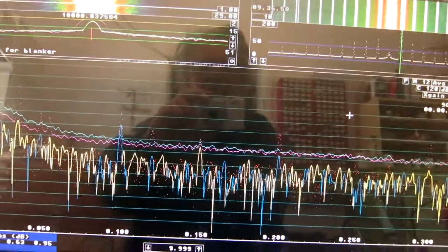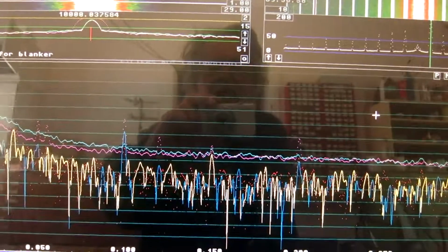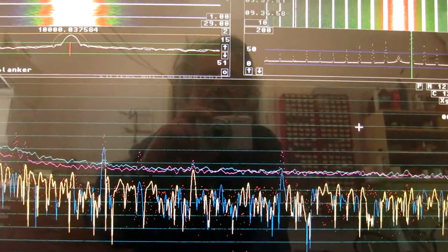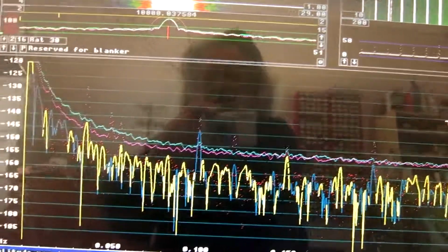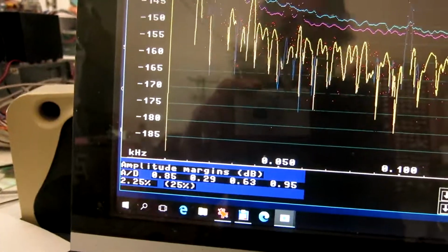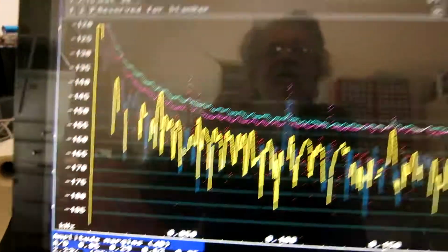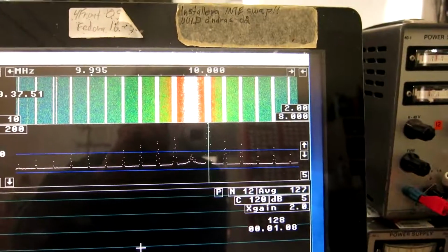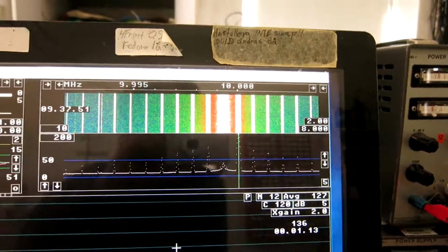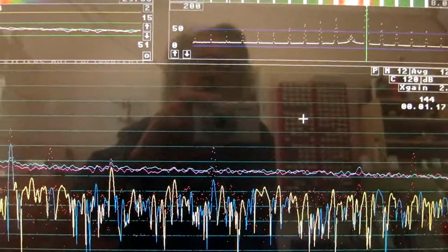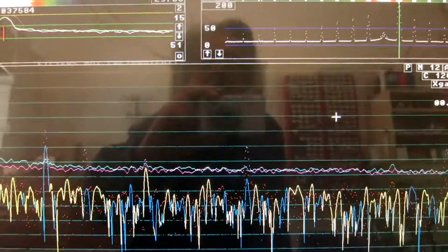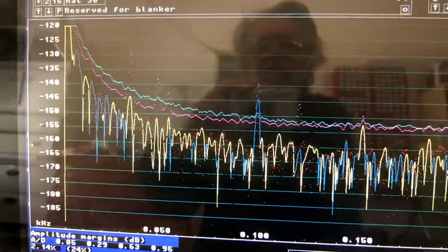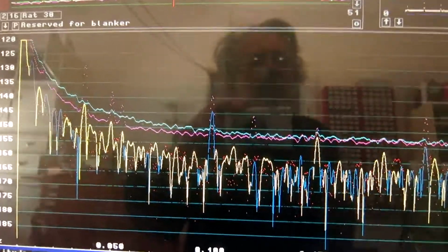I have restarted now with a 6 dB attenuator between the Wenzel oscillator and the filter, and I compensated that by increasing the gain of the sound card by 6 decibels. In total I lost about 4 decibels of the signal to noise ratio, so to get the same accuracy I need a much longer time, but I don't think I need the same accuracy. I just want to have some kind of a look on this. But I have to wait, of course.